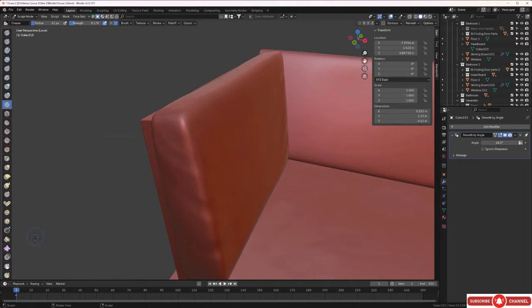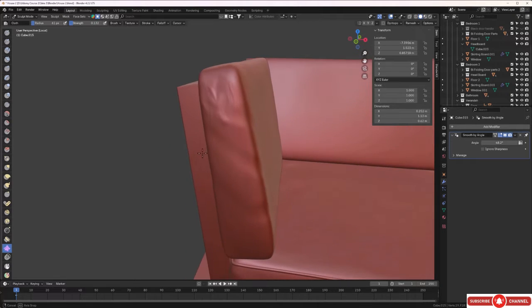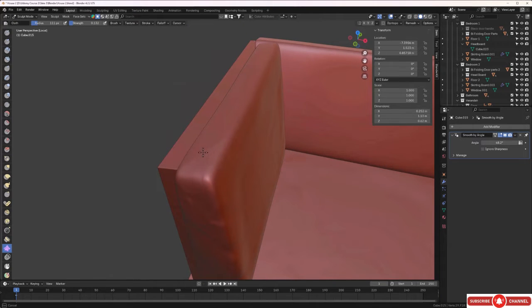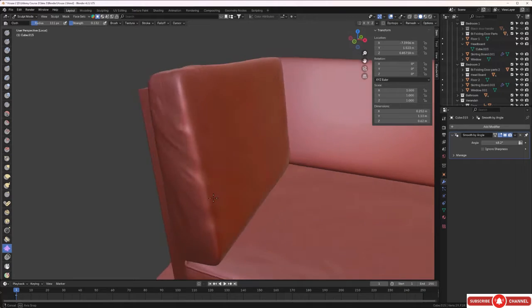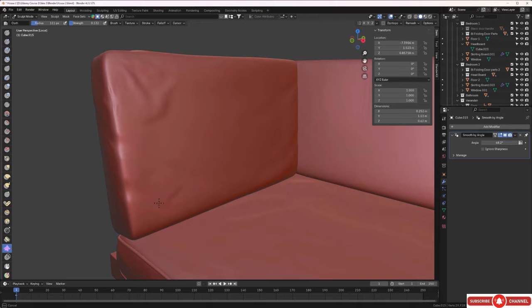Okay, so now let's use the grab cloth brush. Here it is here. And I'll keep the auto smooth quite high indeed. And I'll keep the radius and strength where they are for now. And let's have a play. Maybe I'll increase, I'll just press Control Z. And I'll right click and increase the radius a bit. And let's try that again. Maybe one down here too. And maybe one here. And let's see what we got. Also now I'll apply some to the surface here. And maybe one here too.